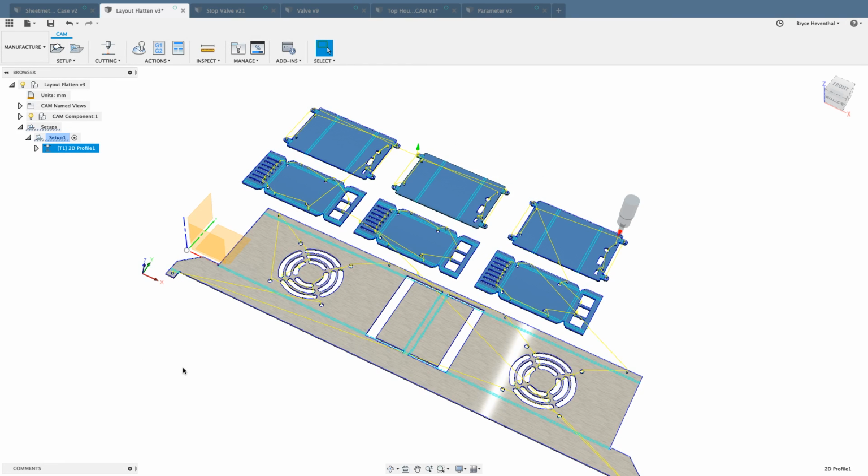So I quickly added these jobs to the same job that I already had done. And both of these are coming from different Fusion 360 designs. So if someone was working on this casing and made some changes, I would get a flag. All I would need to do is update, regenerate my toolpaths again, and we can quickly send the G-code out to the shop floor to start cutting on our water jet again.